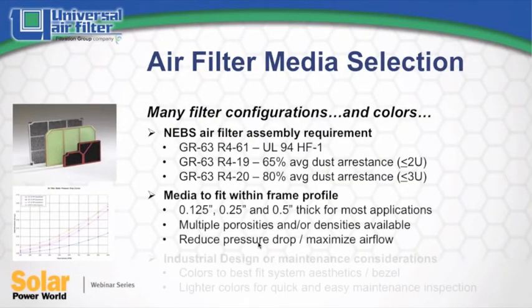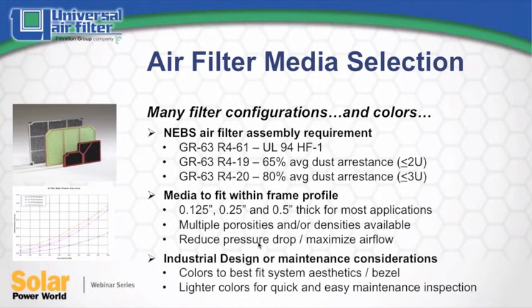When it comes to media, there are many filter media choices out there, so you need to choose the most appropriate when it comes to flame resistance, dust capturing as applicable to the cabinet size. Pick the most suitable media for the frame size you've selected. Know your airflow restriction requirements. Match equipment look and feel, and think about preferences for minimizing or maximizing dirty look for maintenance inspections.